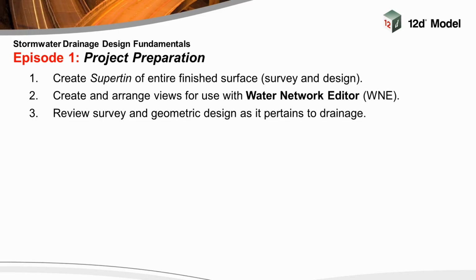Step 3 then is to review the survey and geometric design as it pertains to drainage, specifically the surface drainage of the survey and design tins. Now obviously this is going to be your job whether you're using 12D or not. It typically falls into the drainage designer's realm to review the design before you even do any work at all, to make sure that what you've been provided and asked to respond to as a drainage designer is going to work. So I'm merely going to show you a few tools you have available to conduct this review in 12D.